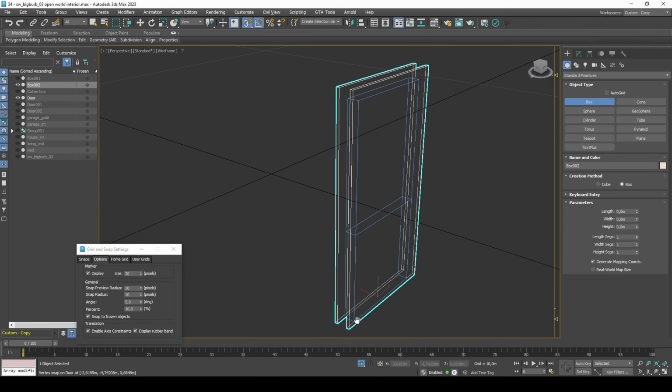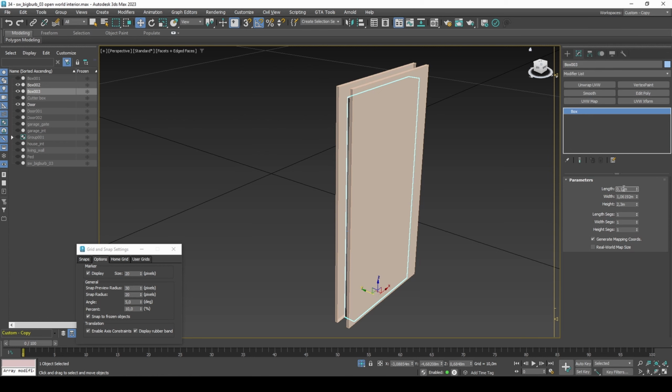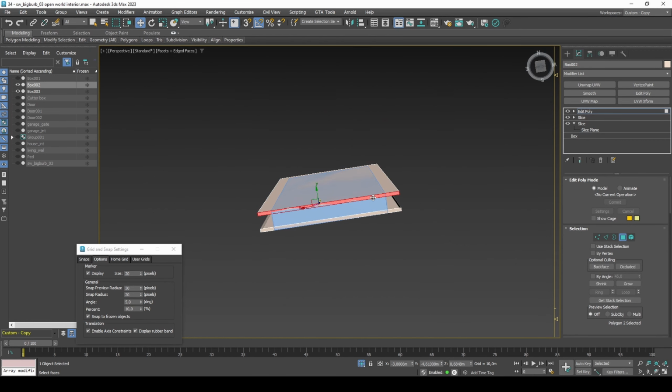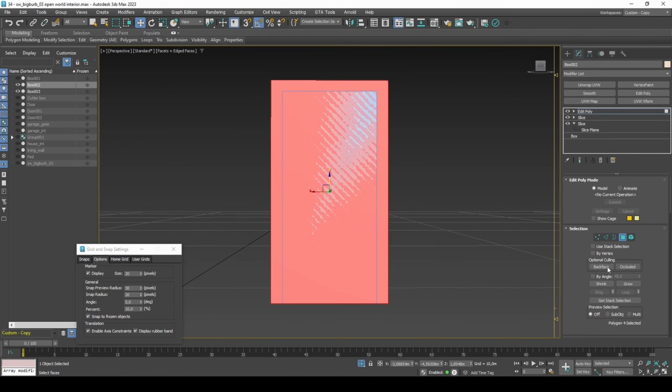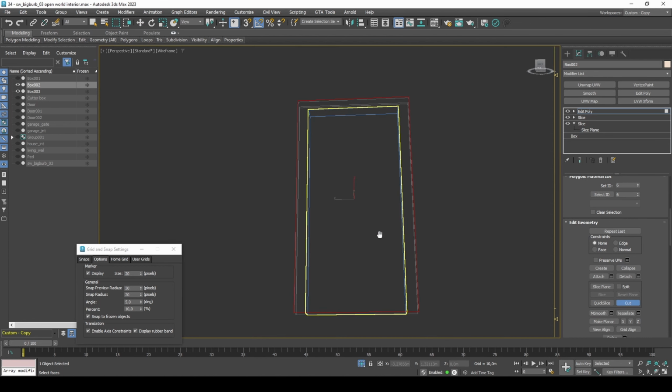Create another box snap to the door. Make the length 0.18. Isolate the box and the doorframe details. Remove the frame bottom faces. Use the cut tool to remove the inner part of the doorframe details, and the box to help guide the cut positions.